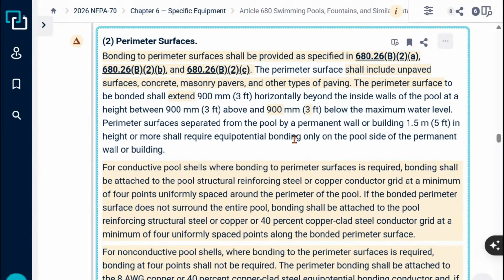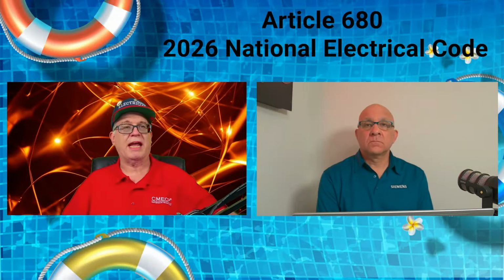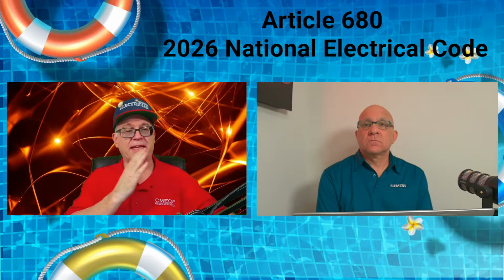So if our perimeter surface is separated from the pool by a permanent wall, and that wall is at least 5 feet high, I don't have to go fully 3 feet out. That 3 feet can actually stop, maybe at 2.5 feet, at that wall, because that wall is a 5 foot barrier. It's breaking that 3 foot measure.